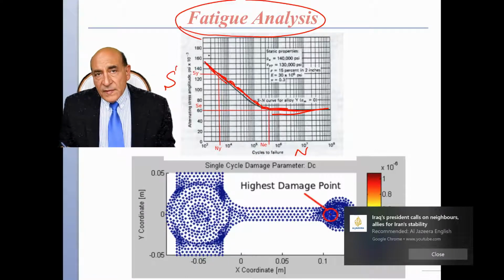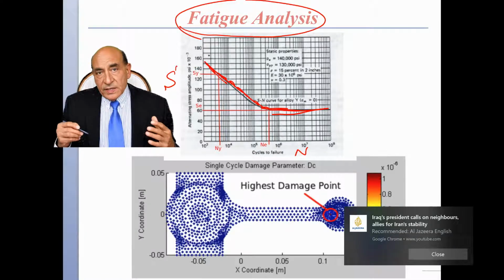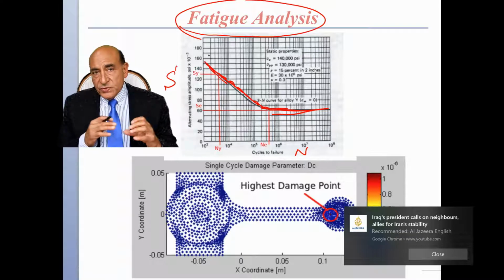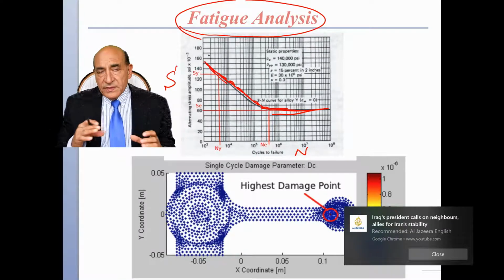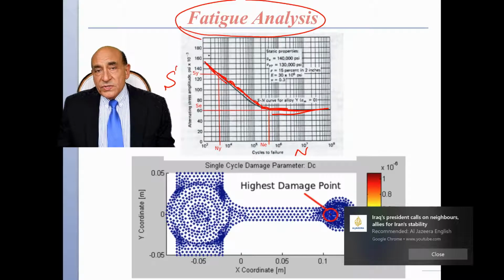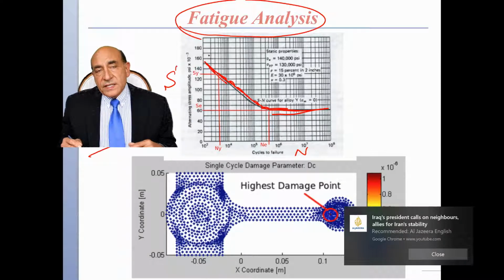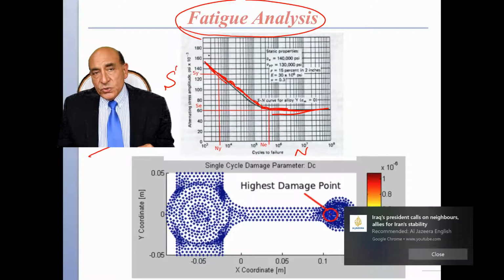However, with this type of analysis, we're going to find many fluctuations in the rod, and there are so many points that if we take a volume element in every different piece of the rod, each volume element is going to see different fluctuations. Then we use another MATLAB program that we wrote, and this MATLAB program is linked to COMSOL to determine the amount of damage accumulated per cycle.